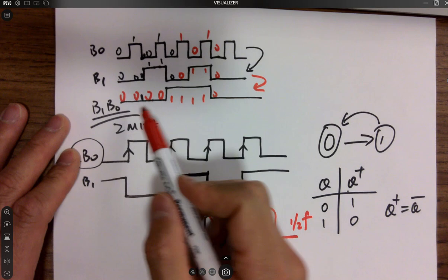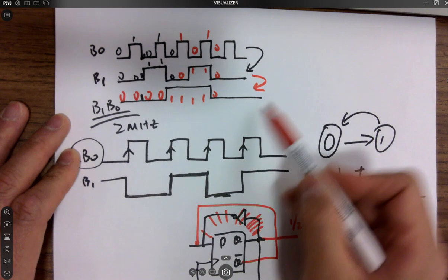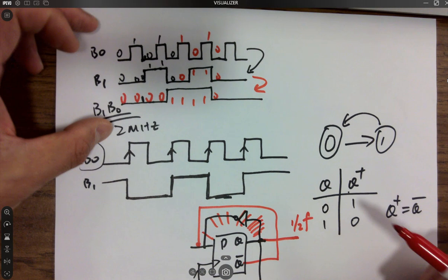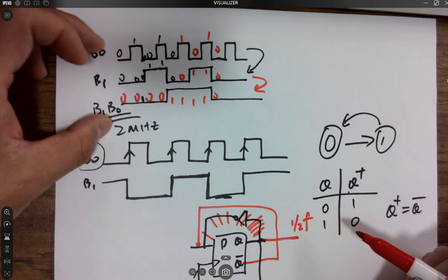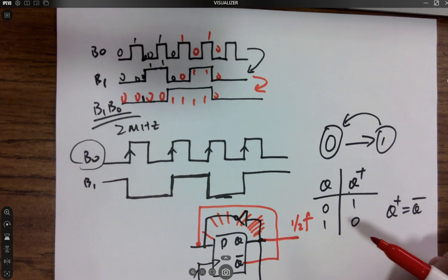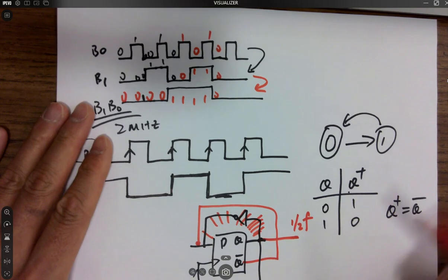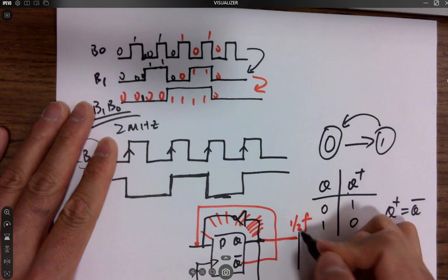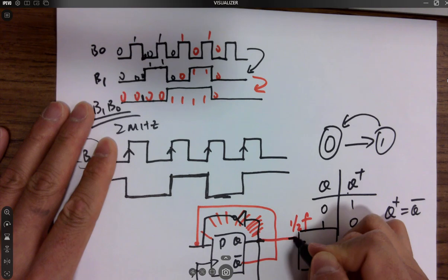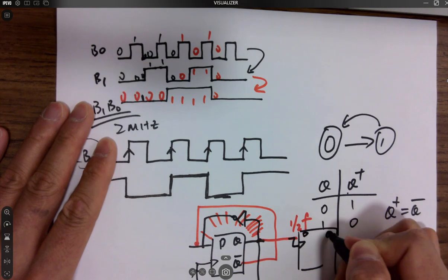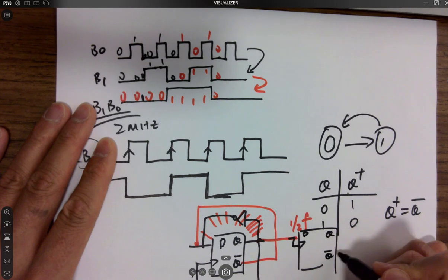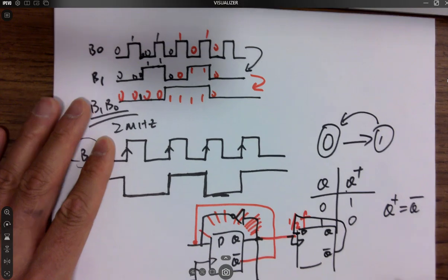So eventually you can form a waveform like this, and you combine those bits together, and you are getting a counter from that. What's that? Well, if you're going to add an additional bit, the Q of the previous bit would go into the clock of the next one. Yes. It's a clock, right? I got a D here, Q, Q naught. Right?